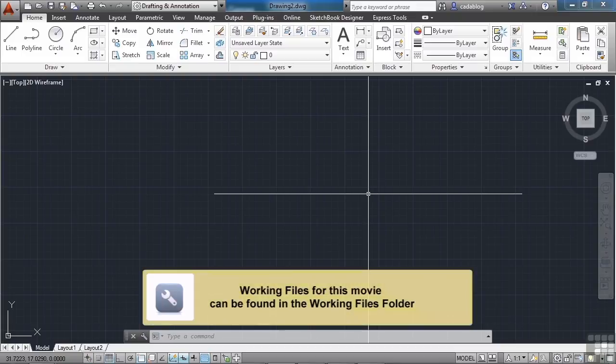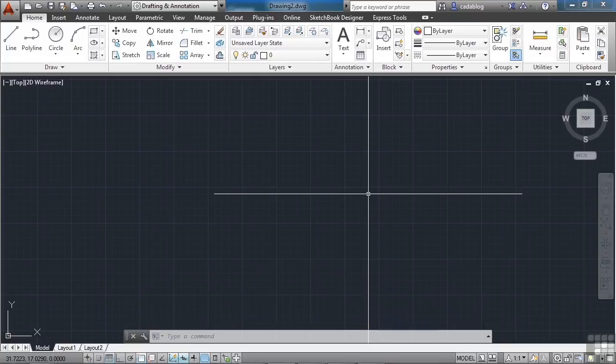When we drew on the board, we would draw light lines that were easily erased, called construction lines or projection lines. AutoCAD has an object type that will help you do this, and it works in a very similar way. You can always use a regular line, but there are tools that are meant to be used in this way. These commands are construction lines and rays. They both work the same way, with slight differences between them.